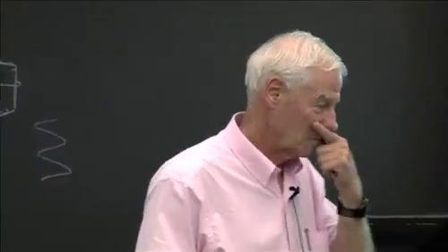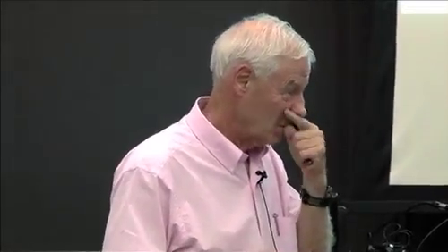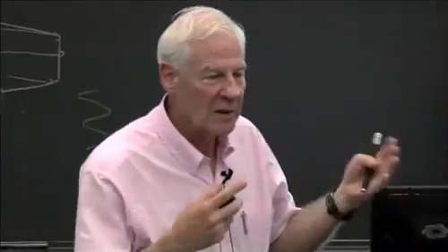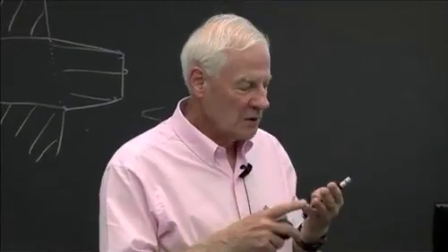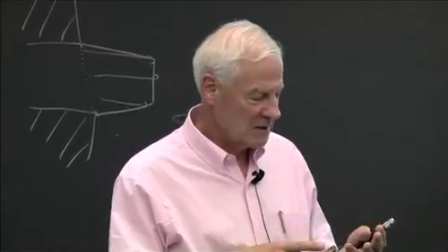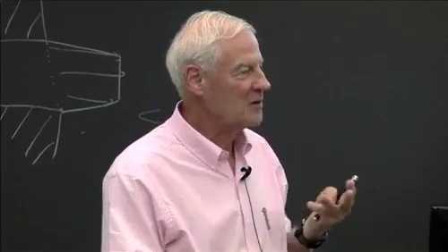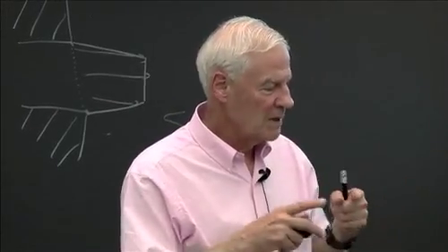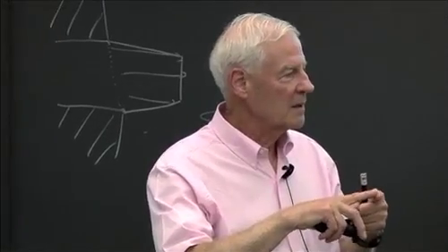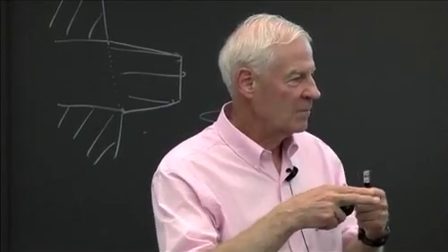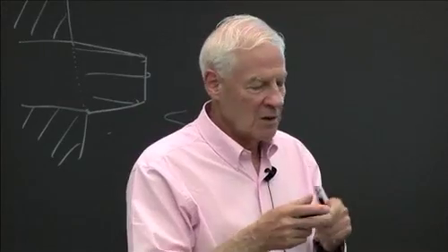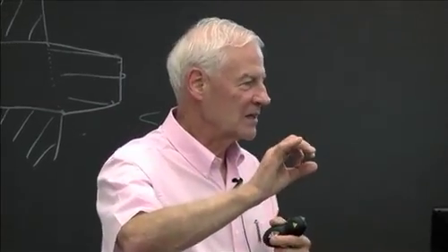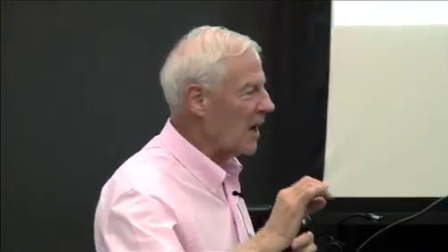Yeah, question? It seems like beam steering is never a problem with this type of what? Beam steering, okay. What about the beam steering? When we do our shock tube experiments, the problems are always the same: beam steering, interference emission, interference absorption. They're always the problems we have to deal with. Beam steering: the light's going across, high pressures, high density gradients, the beam moves around. You have to have a hole on the other side that lets the light go out, and you have to have optics that collect all the light. So we deal with this.